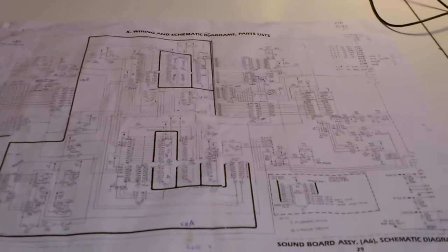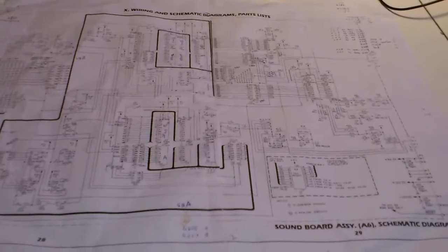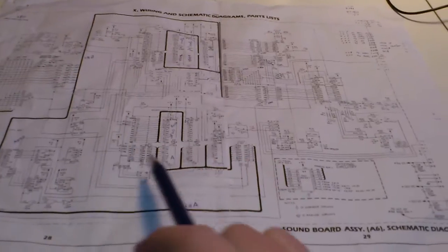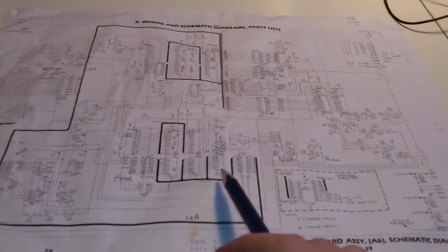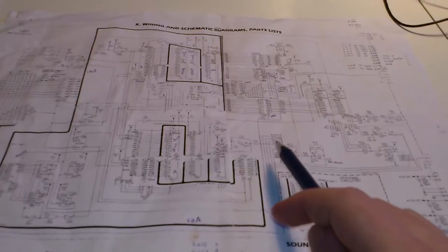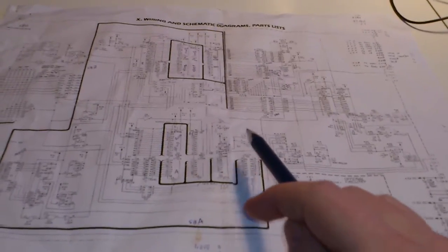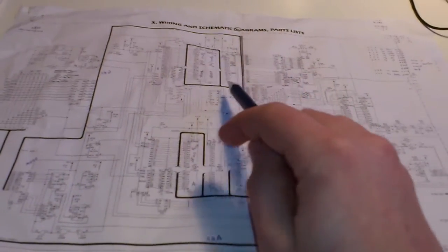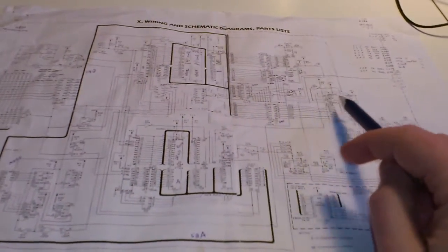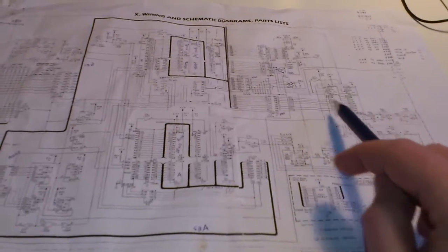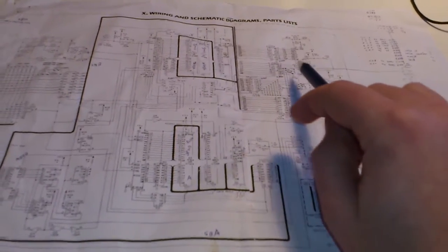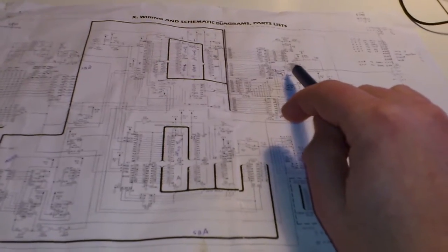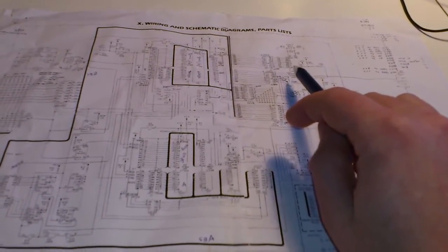On a high level, what we see on that card is that there are basically three sound generating entities. The first entity is a CPU, a 6502 Rockwell, which is just working with a digital analog converter to make typical sounds. Then there is a second CPU, a 6502 as well, with a little bit more memory, which is controlling a programmable sound generator on that side. So this is playing tunes. And then we have an SPO 250, which is a voice synthesizer, and this component is producing the voice.